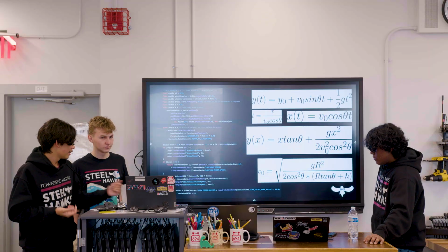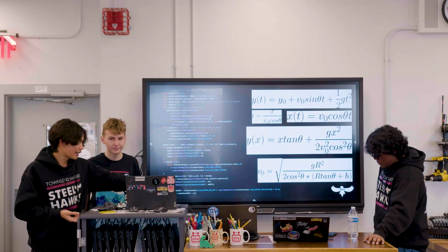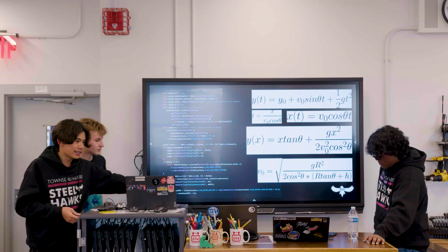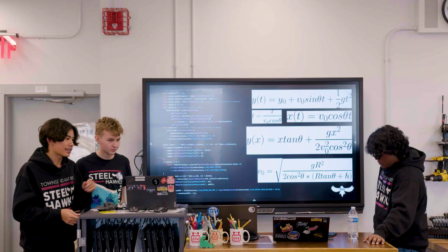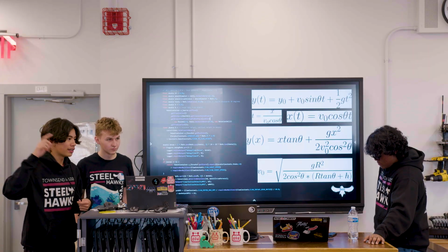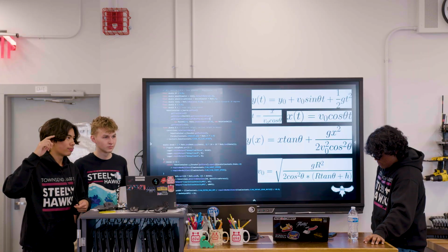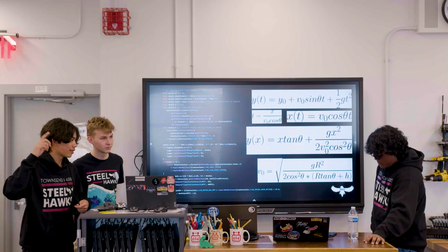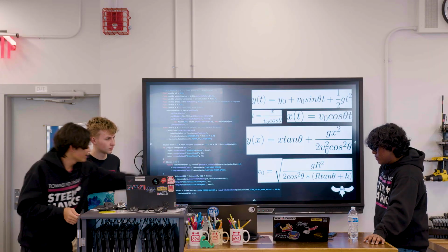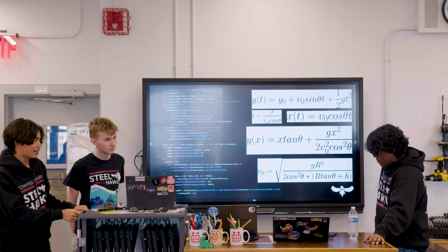So if let's say our max output is 1,000 and our initial velocity is 600, you get 0.6, and then you would use that to run the motor at 60% of its full power. And then we add kS to account for static friction.